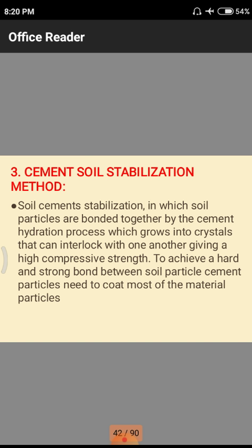After mixing with some quantity of water, we have to spray that water on the surface, and those bonds will form. Calcium silicate hydrate gel will form automatically. Due to that calcium silicate hydrate gel, we will get compressive strength as early as possible. Normally cement has an initial setting time of 30 minutes, and the maximum final setting time is 10 hours. Likewise, initially it will gain strength.